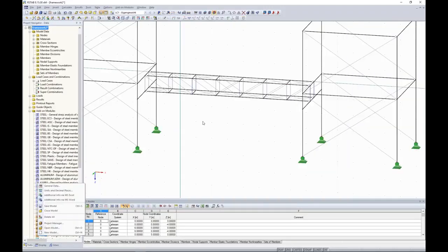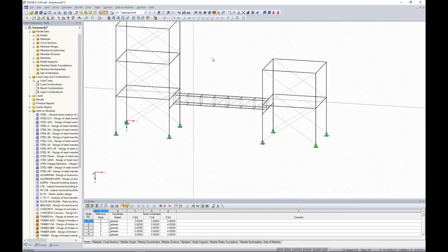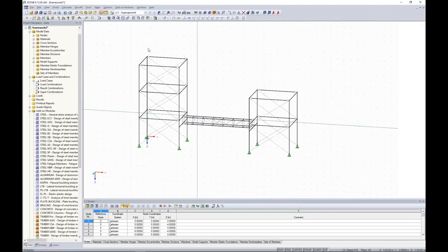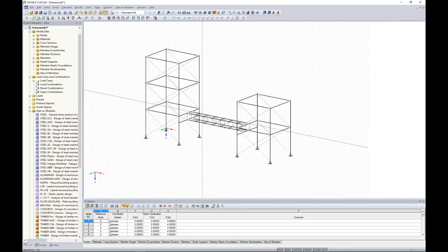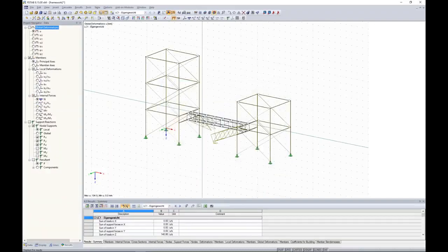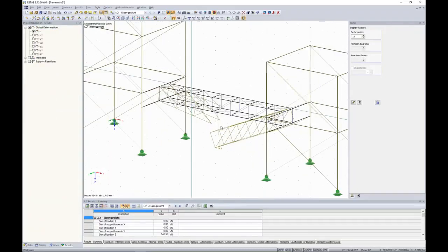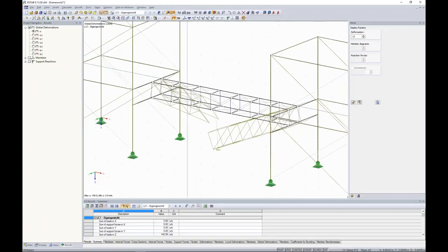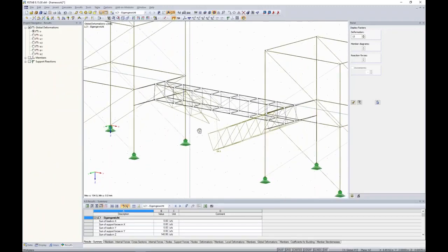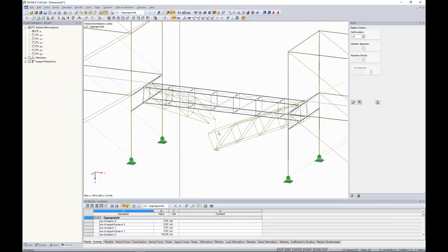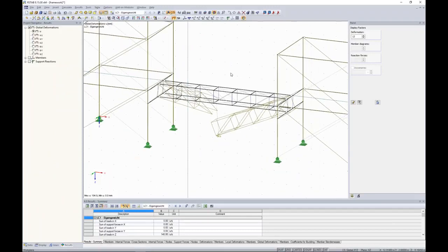That's framework number 2. It's like the same framework on the left side and a smaller one on the right, and these should be connected with this cable duct, and you can just try to calculate the self-weight load case. And as you see in the graphic, the deformation looks quite strange. It looks like the cable duct is actually not connected. And what's the reason for that?